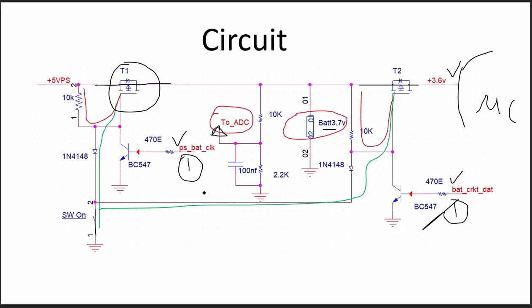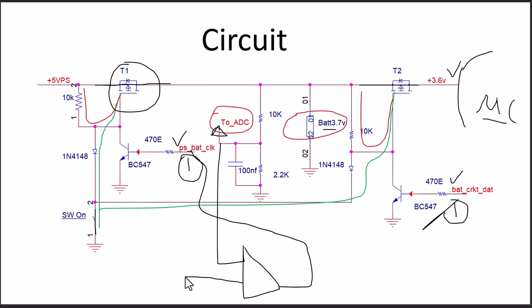In this way we can have the soft switch-on circuit arrangement, and we can also control the battery either from the microcontroller, or we can use some comparator to have that arrangement to charge; this is a reference, V reference. Either you use some voltage divider network or potentiometer to set this one.